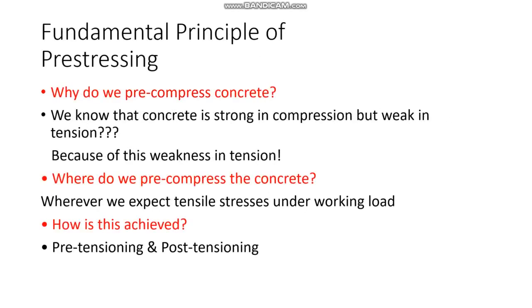But why do we pre-compress concrete? As we know, pre-stressing is the intentional creation of permanent stress in a structure or assembly for improving its behavior and strength under various service conditions. Ordinary concrete consists of concrete and mild steel as basic components. The compressive stresses are borne by concrete, while tensile stresses are borne entirely by steel. The concrete only acts as a binding material, and it does not take part in resisting the external forces.